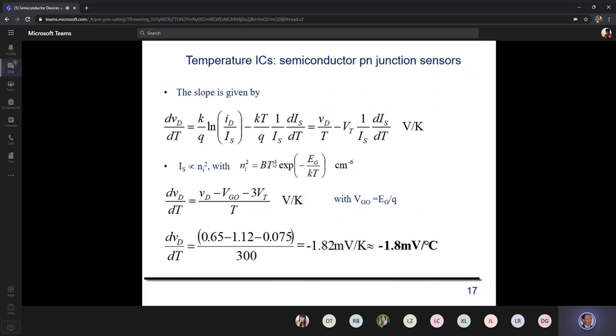So this is a term to which the saturation current is proportional. When you take the log, of course you have the log of a constant that disappears in the derivation when you take the derivative. Then you have the log of T cube, and then you have minus the log of the exponential of Eg over kT, that makes minus Eg over kT, okay?